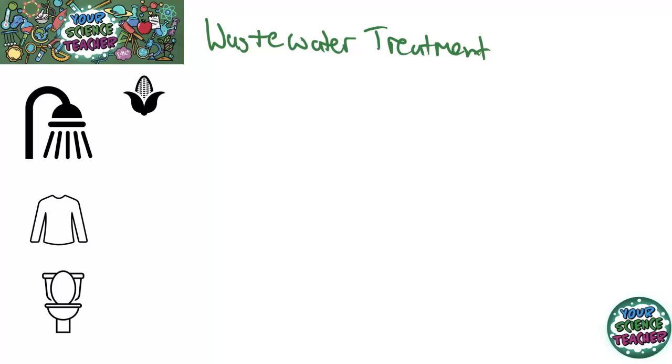So as you can imagine, we have a lot of wastewater to process, and it always takes place with these key steps. The first step being the water is screened, and this screening is a really important process. It removes all the really large insoluble objects that are in that wastewater.